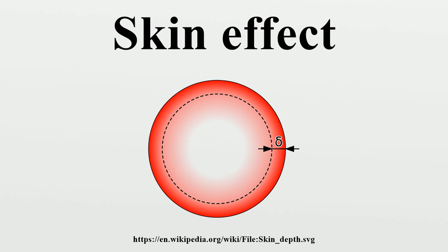This behavior is distinct from that of direct current, which usually will be distributed evenly over the cross-section of the wire. The effect was first described in a paper by Horace Lamb in 1883 for the case of spherical conductors, and was generalized to conductors of any shape by Oliver Heaviside in 1885. The skin effect has practical consequences in the analysis and design of radio frequency and microwave circuits, transmission lines, and antennas. It is also important at mains frequencies in AC electrical power transmission and distribution systems.